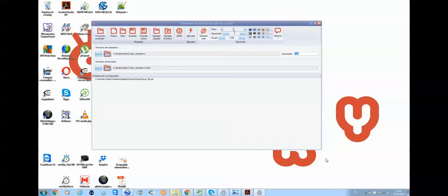Each value of these 3 points: when we put step 7, it is the number of levels where we create points, and after putting 7, press enter. The spacing is the minimum distance between points created at the first level. In the first level, the points will appear with 2 meters of spacing. Okay. In the second step, the distance will be half, 1 meter. The third level, half of the level before.